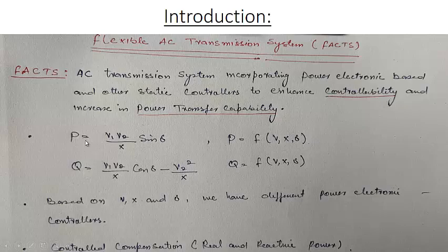If we change this real power, there will be no change in reactive power, and if we change reactive power, there will be no change in real power. But in most of the power electronic converters, you will see that they change dependently on each other. Because if you change Q, P will automatically change. If you change P, Q will automatically change. We'll see how this change will take place.